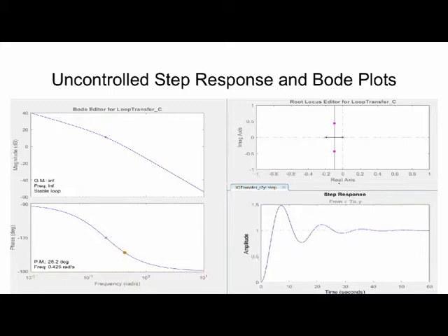Another significant consideration regarding our design would be the steady-state error, but as our system already has an integrator, it is already fixed to zero, and adding an additional integrator would only create overshoot. Other minor considerations in our design were the settling time and rise time. While not very important to solving our problem, it was still desirable to keep these characteristics in reasonable ranges so that you don't wind up waiting minutes for the quadcopter to land.